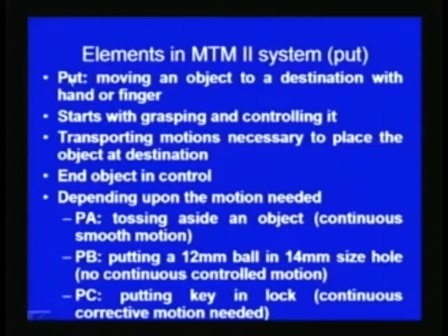The put is another element, which involves moving an object to a destination with the hand or fingers. It starts with grasping and controlling the object and the transporting motions necessary to place the object at the destination, and ends with the object in control. Depending upon the motion needed, the put element is classified as PA, PB or PC.